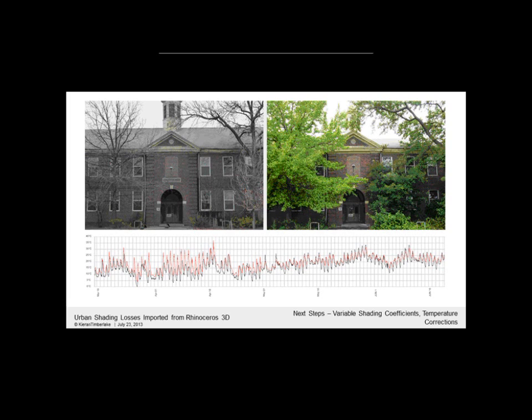We also have quantitative experience with building 661 in particular, where we've embedded temperature sensors in the exterior envelope to examine the transient thermal behavior of the existing masonry construction. So what you see in the graph is a comparison of ambient air temperature in black with exterior surface temperature of the east-facing brick wall.